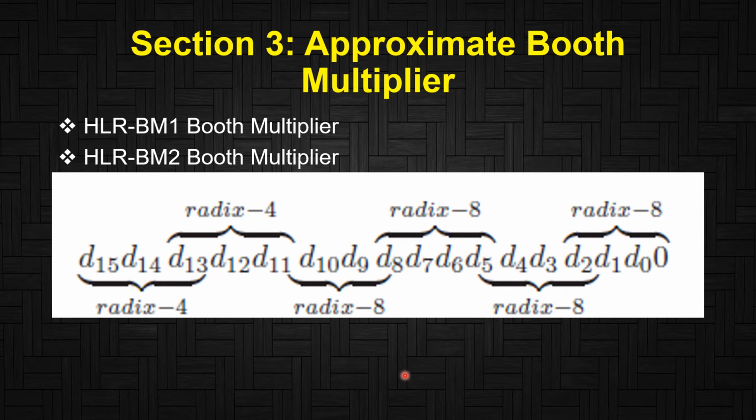This method complements the error in the partial product reduction process and still maintains the error difference of 1 against the approximated values. Therefore, if two Booth multipliers are designed using R8-ABE1 and R8-ABE2 respectively, then the error in the R8-ABE2 based Booth multiplier will always be less than that of the R8-ABE1 based Booth multiplier.